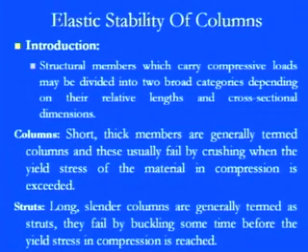And these usually fail by crushing when the yield stress of the material in compression is exceeded. So you see here, when you are simply compressing, due to that compressive part, if there is crushing, it means the layers are crushing into each other, simply overlapping each other. And if the yield stress is reached, we have a failure in these columns. So here we are defining in terms of their dimensional part.